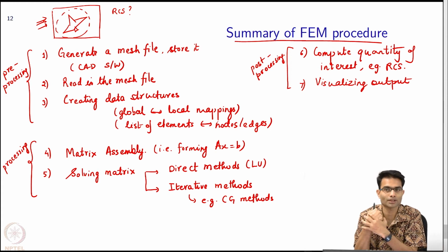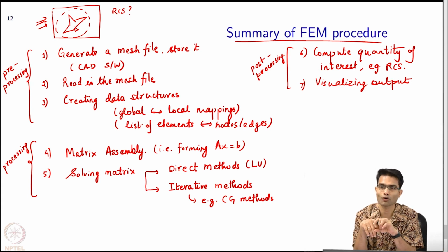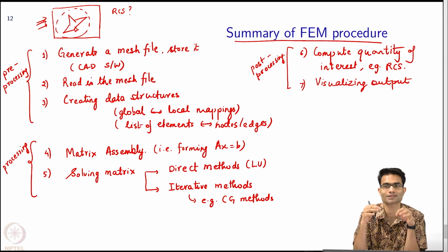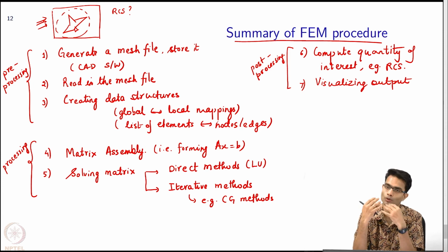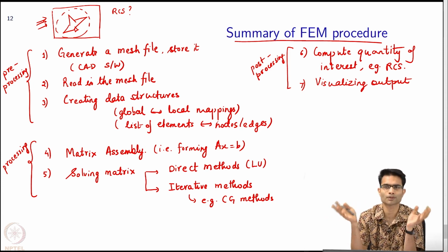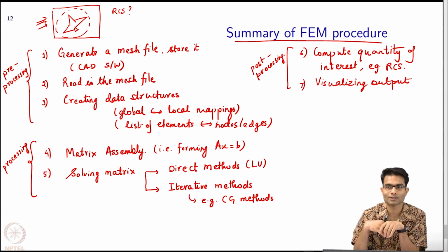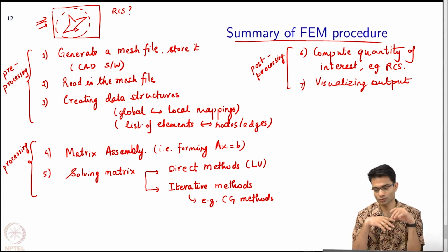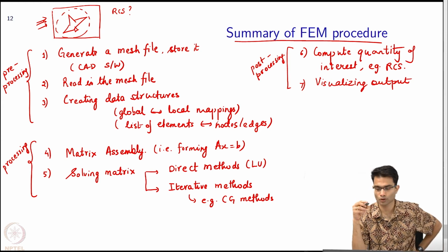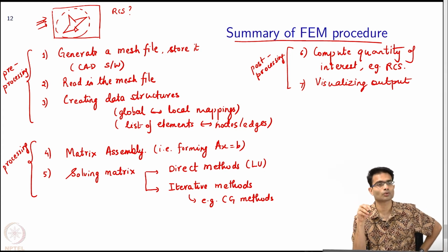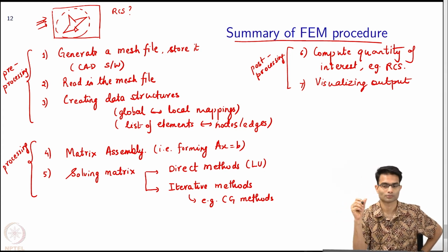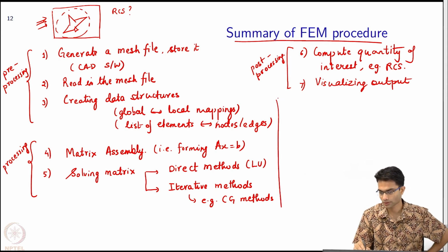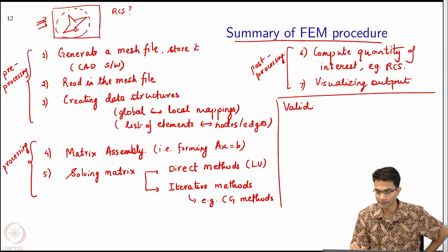Numerical convergence is something that you have to do anyway, but it may be that you have converged numerically to the wrong answer. I mean, you have coded a consistent set of equations which are wrong. Like let's say you forgot the k0 squared term altogether. So it will give you numerical convergence, but you have solved Laplace equations from Maxwell's equation. So what would you do now? Very critical step in any computation. Right. So, what you need to do is validate your code against a known solution. Right. So, this is extremely important. Validate.